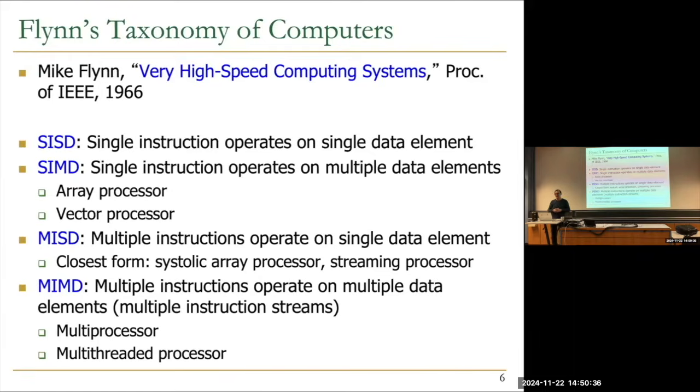With SIMD, and this is one of the major benefits of GPUs, or vector processors in general, assuming you have the parallelism in your program, you fetch and decode the instruction only once, and you unleash 1 million operations, right? So the efficiency of this is much better. Essentially, the overhead of an instruction is really amortized over many data elements. Okay, and then there's a couple of other things on the other dimension, multiple instruction data.